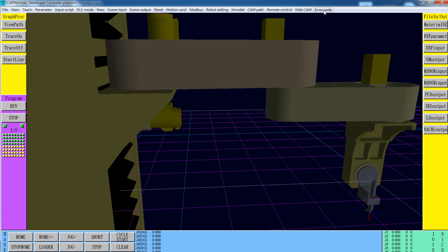Sometimes, for fast go back to that position, we can also press Control F2 to set a fast return point marked by a square, a cyan or a blue square. You can set plenty of return points by means of the Control plus F2 function key.